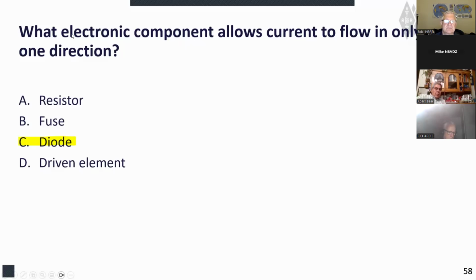So when you're engineering a power supply circuit, you have to account for that 0.8 volt drop. Some of the more sensitive ones that you use for detecting signals can be 3/10ths of a volt or less. But that's again beyond our pay grade.